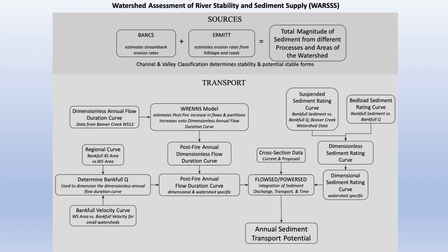And that transport is based upon the channel shape, the channel slope, and roughness and a lot of other things. So what you're trying to do is look at how much more water you have coming in, how frequently that comes through, and then route the sediment through with that new amount of water given the specific channel shape.